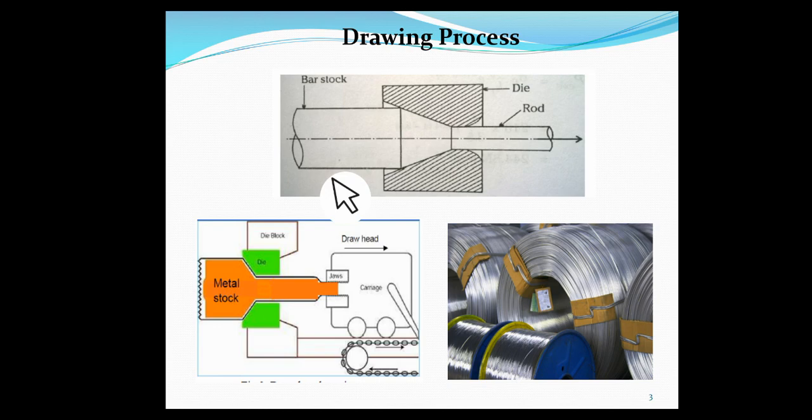Remember here in operation, the end portion of the rod will be squeezed or cut to a certain length, then it will be inserted into the die. Clear. Remember, the end portion of the workpiece material will be cut or squeezed for a certain length, then it will be placed inside the two dies. This one we call a hollow cross section.